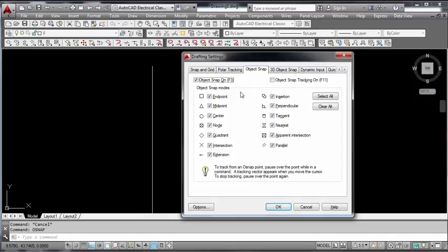Why it is catching is, there is one option called nearest. The symbols you can see here, nearest. So if nearest is on, wherever your mouse moves, it will try to catch the nearest point. Now this is midpoint. See, these are all nearest. This is endpoint. If you have to catch the endpoint, you have to zoom in and catch. Otherwise, you take the nearest point.